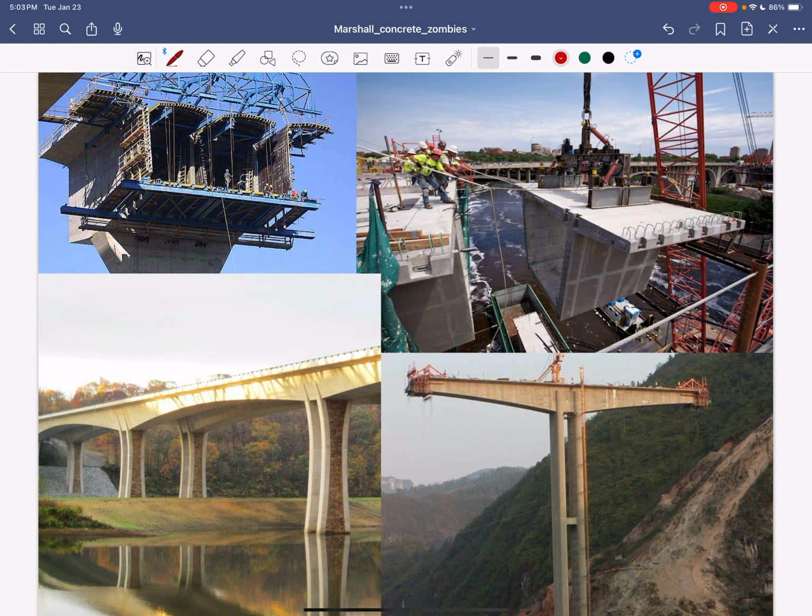And finally, I specialize in a certain type of concrete bridge, and it's called a precast segmental bridge. So the Stillwater Bridge, the new one down south towards the cities, is a precast segmental. The I-35 bridge, the one that replaced the steel one that came down, is also now a concrete segmental bridge. So these are really cool. We build them out from the pier, and then when the other pier comes into play, we connect them, and they can be built with really, really tall columns without disturbing the earth below. So that's kind of cool.